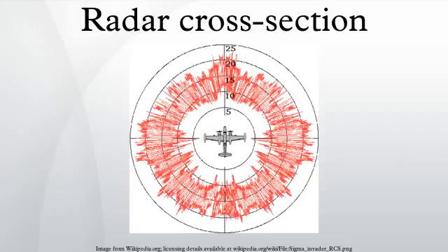In some cases, it is of interest to look at an area on the ground that includes many objects. In those situations, it is useful to use a related quantity called the differential scattering coefficient, which is the average radar cross-section of the set of objects per unit area. Where RCS_i is the radar cross-section of a particular object, and A_i is the area on the ground associated with that object.